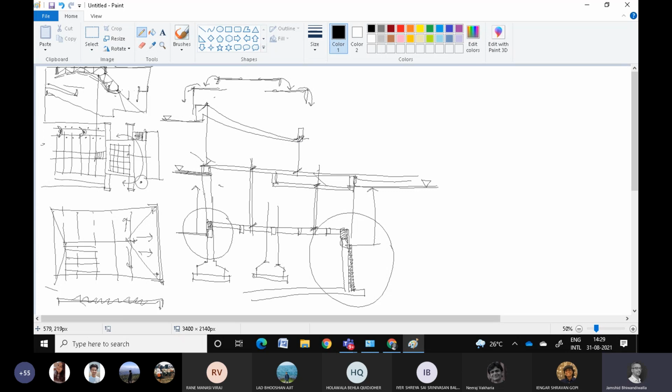So this is a beam bottom. If there is a column that is coming up from here, then one should know that this is the level at which the work needs to stop, and this level needs to be given. And this is all in reference to plus minus 0.00. So is this very clear to everybody that in sections, one is the floor to floor height that is to be given, and the other is the beam bottom levels that have to be given. These are two expected areas.